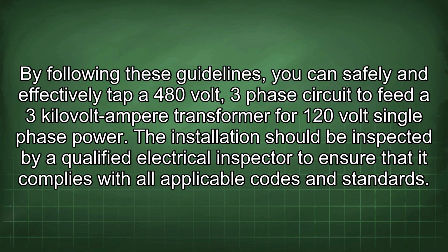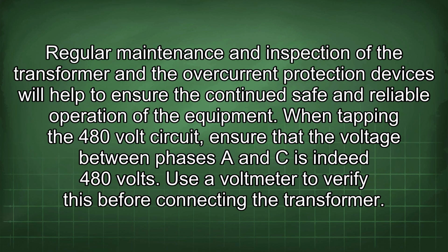By following these guidelines, you can safely and effectively tap a 480-volt three-phase circuit to feed a 3 kilovolt-ampere transformer for 120-volt single-phase power. The installation should be inspected by a qualified electrical inspector to ensure that it complies with all applicable codes and standards. Regular maintenance and inspection of the transformer and the overcurrent protection devices will help to ensure the continued safe and reliable operation of the equipment.